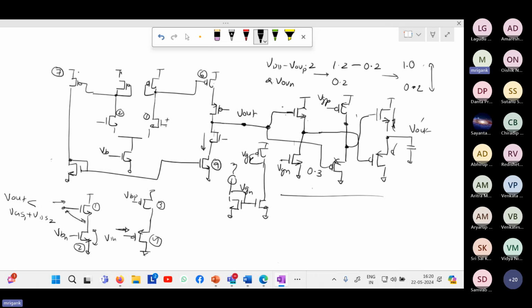If I just look at the independent path, you have one NMOS common drain stage followed by a PMOS common drain. And the other path is a PMOS common drain followed by an NMOS common drain. So each individual path is two complementary common drains back to back, a cascading of two common drains.